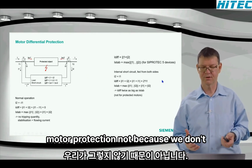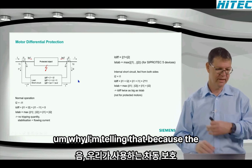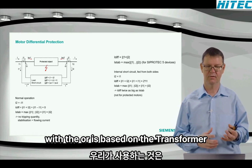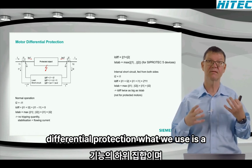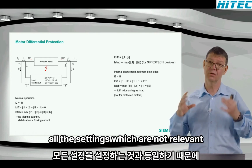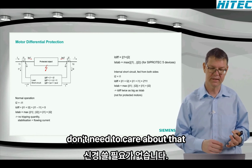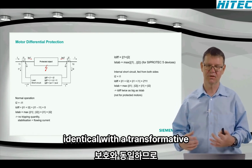However, for the motor protection, not, because we don't have an infeed from that side. Why am I telling that? Because the motor protection function we use, the differential protection, is based on the transformer differential protection. What we use is a subset of functionality and settings. All the settings which are not relevant for the motor, we just take out of the function and they are invisible. You don't need to care about that. But basically, the function itself is identical with the transformer protection.